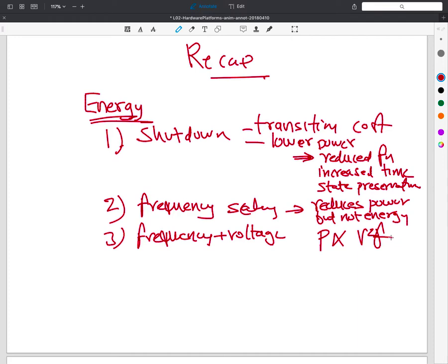So you kind of try to combine it together. Now the complication that I pointed out was that usually processors give you a way to change the frequency very easily. Almost all processors you would find have some sort of a register where you can scale the frequency. So the incoming frequency into the clock into the processor, you can multiply it up and down, and then you actually run the logic of the processor using that modified or scaled frequency.